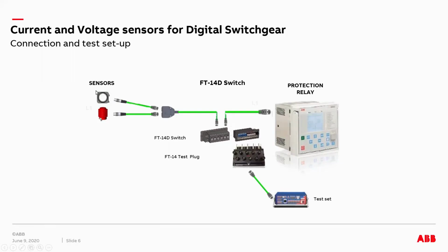This will replace a traditional CT. And down below here, what you see is a voltage sensor. It's basically a voltage divider. This voltage sensor, as we call it, replaces the traditional PT in a switchgear. So these are the low energy analog output devices.